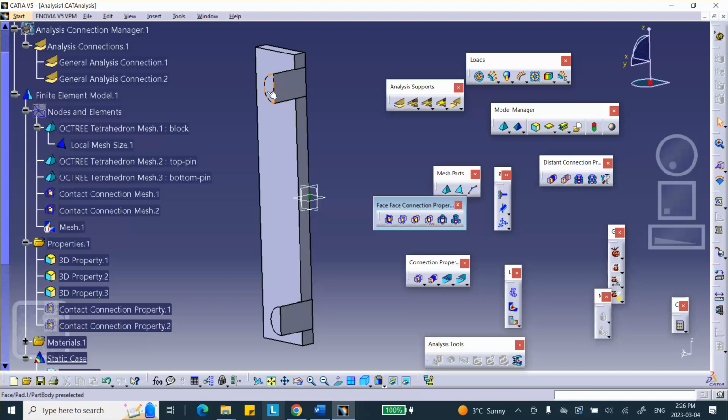Okay. So you have how much force was needed to pull this quarter of a circle up. But there is also not quarters, half a circle up. But there is also the half a circle on this side that we did not model. But there is also the parts on the other side that we did not model. So that's why whatever is needed to pull this thing up, you have to multiply it by 4 to get the final answer, full mark on that particular question.